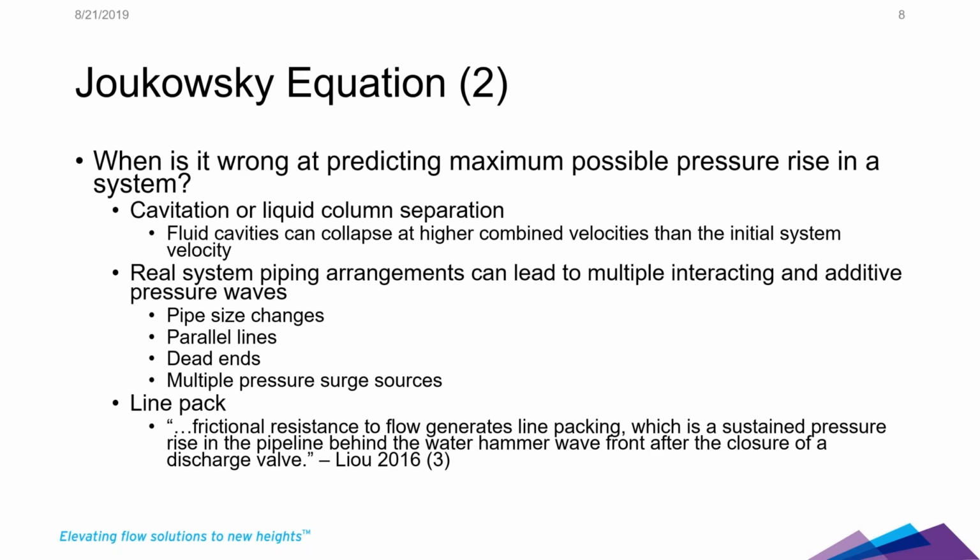Dead ends will also cause larger pressure spikes than Joukowsky predicts. You will have a wave travel down it, and when it hits the dead end, it will actually reflect positively. So you can almost get double your Joukowsky pressure from a dead end.